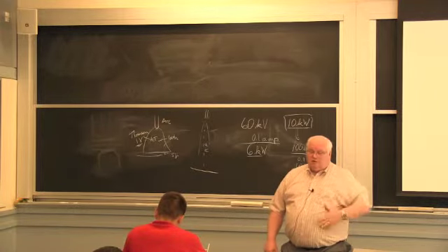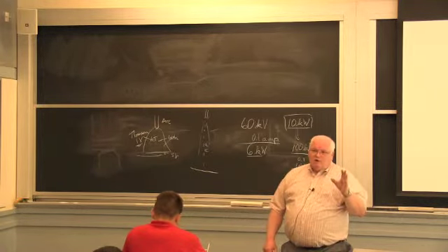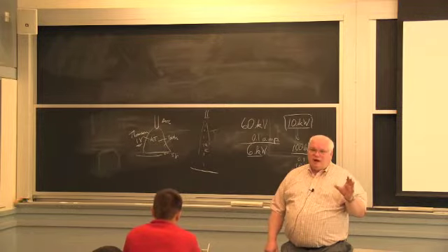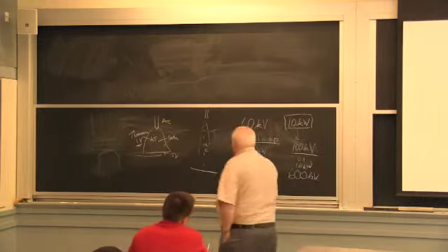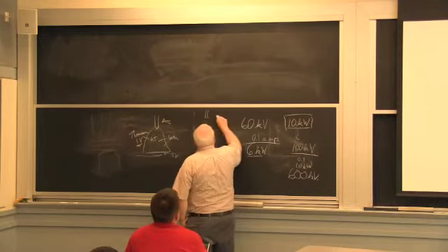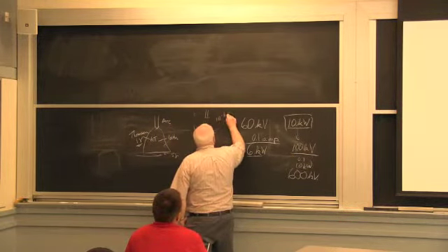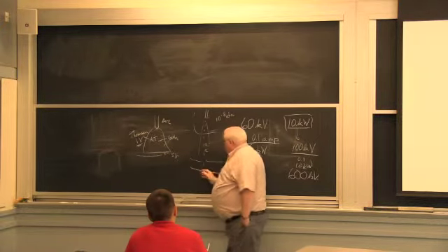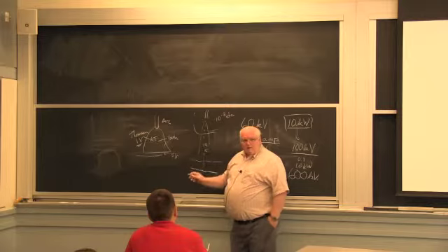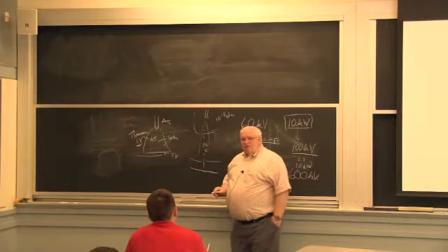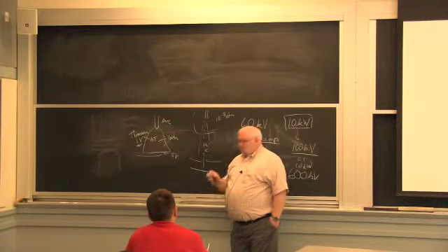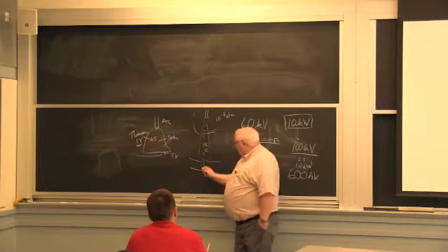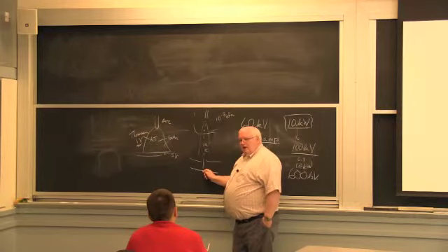Now in that case, we can get into it later, but Ford bought Westinghouse out of vacuum electron beam machines, where you actually generate the beam up here in a vacuum of about 10 to the minus 8 atmospheres. And you have a little aerodynamic window here, which is a continuous leak into your vacuum system, and the beam comes shooting out into the air. The electron beam has some ability to penetrate the air.